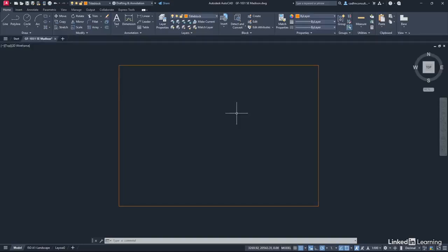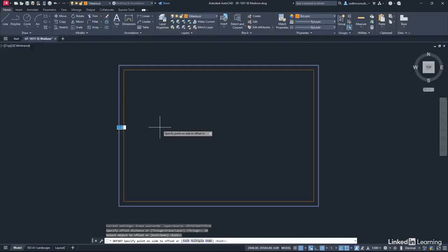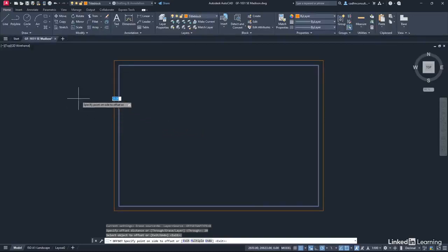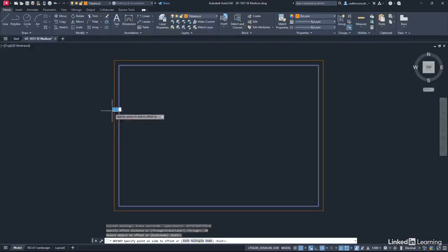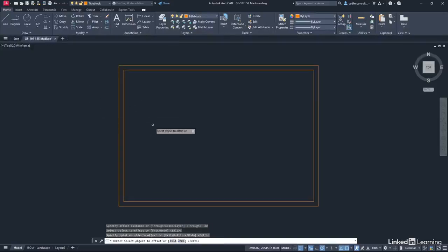Now we're going to develop a really simple title block. In order to do this, we need to use a bit of offsetting, bit of text styles, and so on. You'll see what happens. I'm going to go to Offset on the Modify panel. There's Offset. And the offset distance initially, 20. Press enter. I'm going to select my rectangle, click on it, and move inside. Can you see there's orange on the outside, orange on the inside. So the orange rectangle is the offsetted rectangle, if you get what I mean. So make sure you're inside. The original rectangle is that purple one you can see. So orange on the inside, left click.